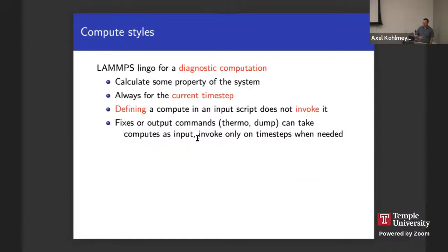Okay, and finally, compute styles. So LAMMPS lingo for a diagnostic computation. So they're calculating some property of the system. It's always for the current time step. And one really important thing to know is that if you define a compute, it doesn't invoke it.